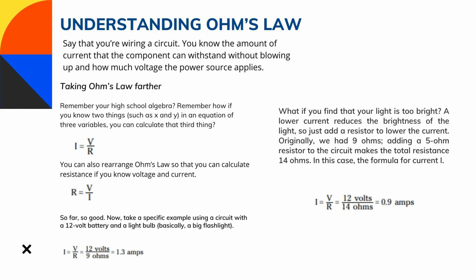Lastly, understanding Ohm's law. Say that you're wiring a circuit. You know the amount of current that the component can withstand without blowing up and how much voltage the power source applies. So you have to come up with an amount of resistance that keeps the current below the blowing up level. Now, in the early 1800s, George Ohm published an equation called Ohm's law that allows you to